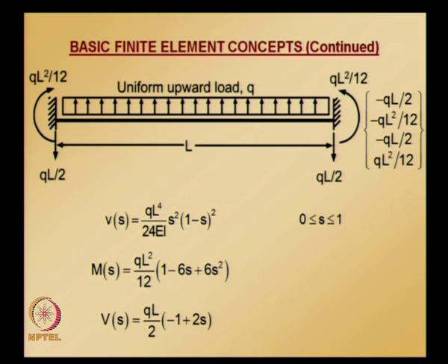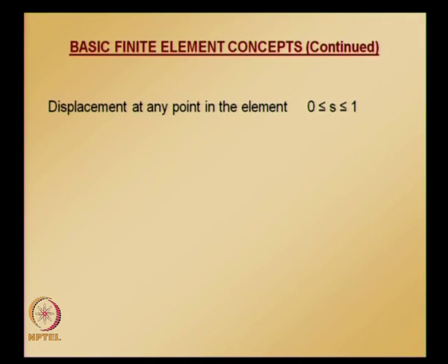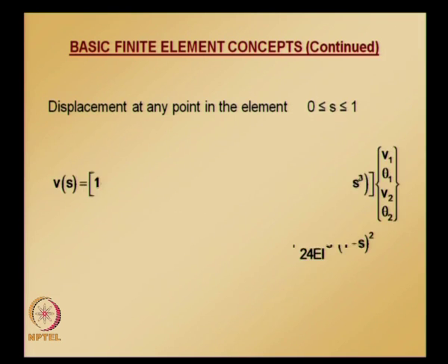And if you want to solve a beam which is subject to distributed load, you can solve as usual using the finite element method and get the nodal values. When you are calculating moments and shears, you add to the solution you get for moment and shears using finite elements the fixed end solution.